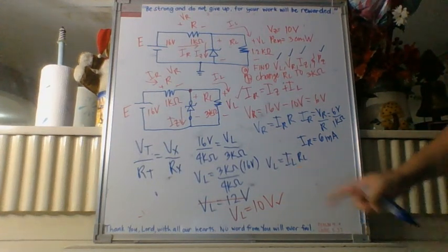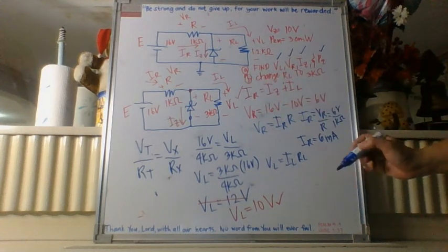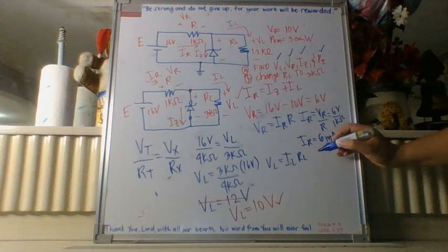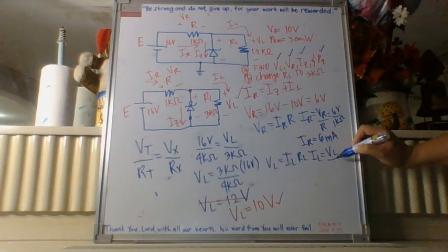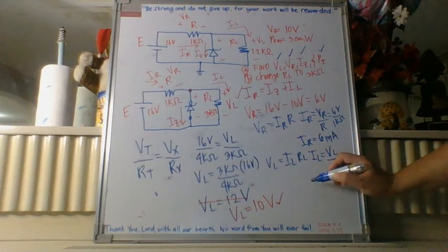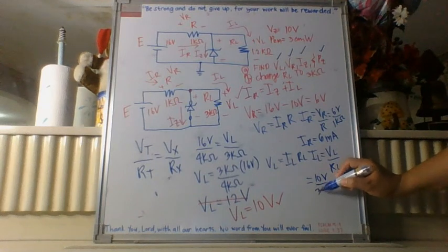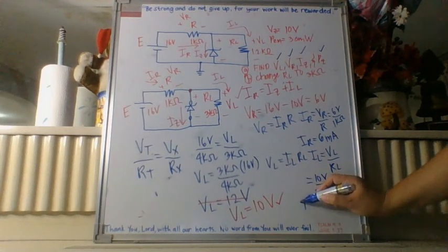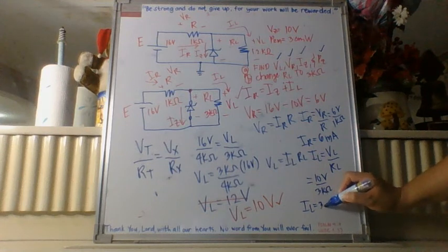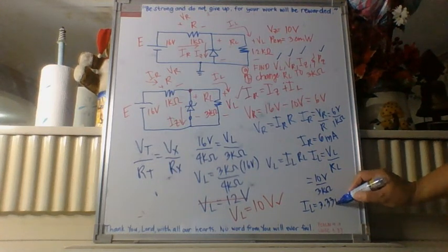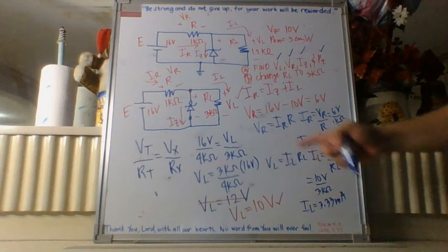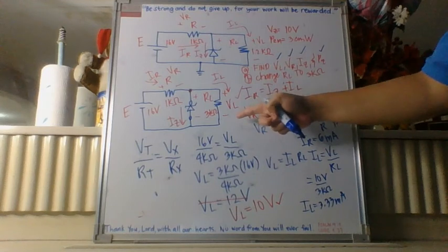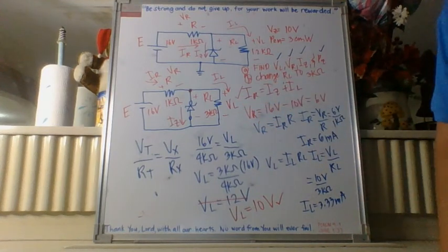I sub L is unknown. R sub L is 3 kilo ohms. We can now rewrite our equation. We have I sub L is equal to V sub L over R sub L. Substituting the values, we have 10 volts divided by 3 kilo ohms. So I sub L is equal to 3.33 milliamperes. Alright? So we have 3.33 milliamperes passing through our load resistor.